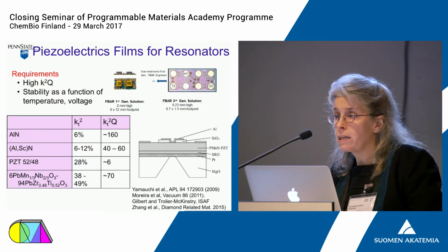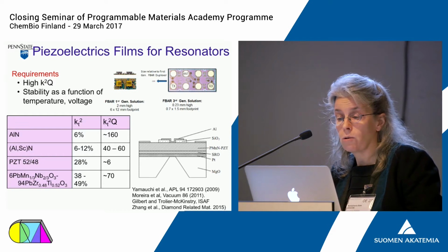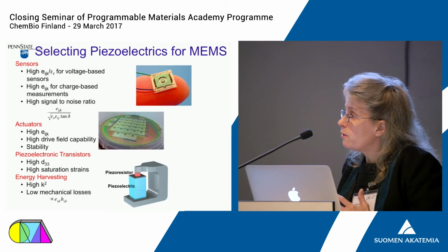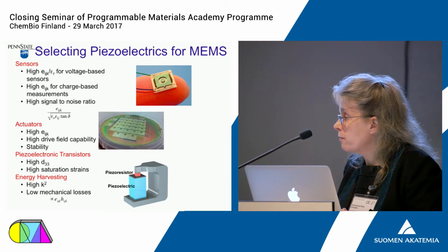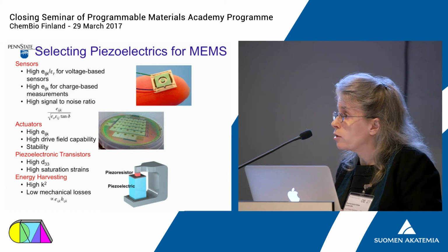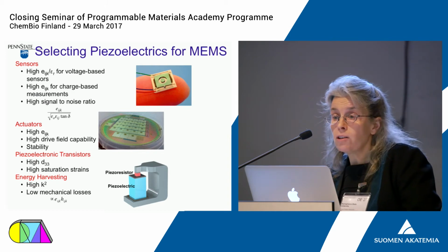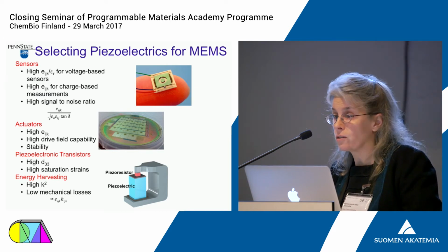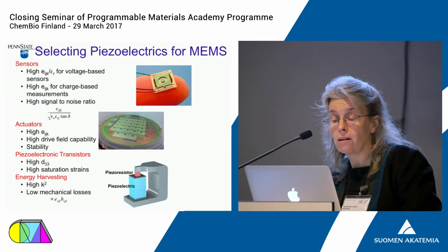We lower the mechanical quality factor and hence lower the figure of merit. So for the cell phone application, non-ferroelectric materials like aluminum nitride win. But because their piezoelectric coefficients are really quite modest, there are numerous applications where they are not so successful. And let me try and motivate that on this slide.